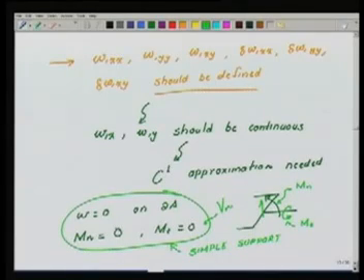But the bottom line is, in all these cases, the work done by the forces on the edge is 0. That's why it didn't come in our definition of the total potential energy. We could have moments and shear forces applied on the edge, then we will have to account for it in the expression for the total potential energy.